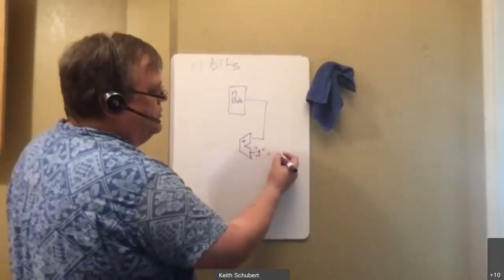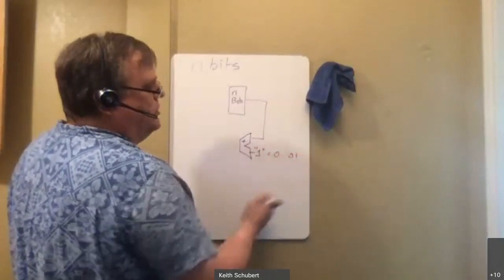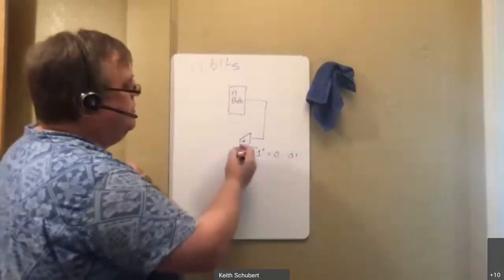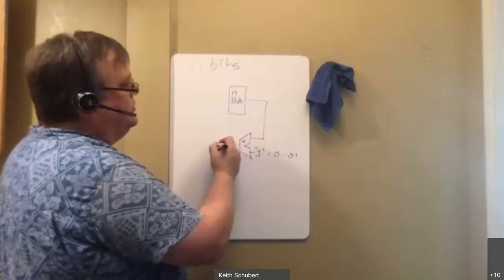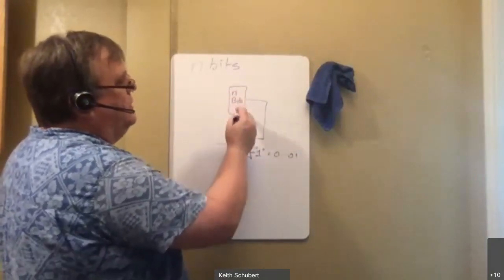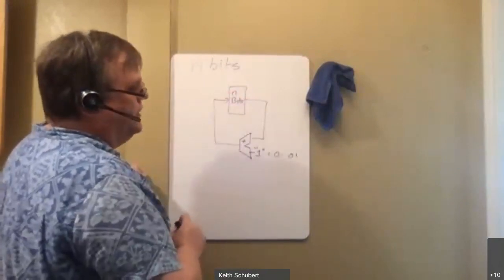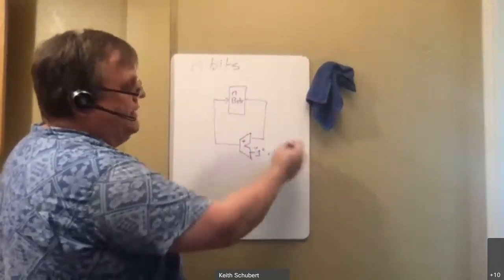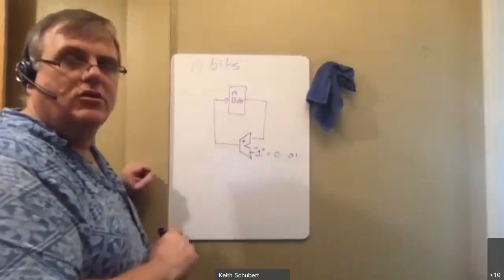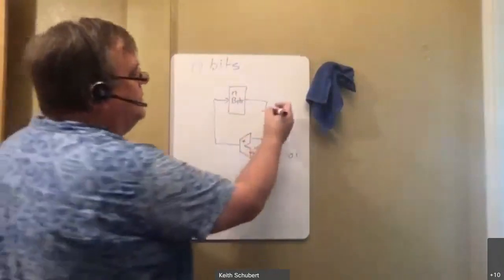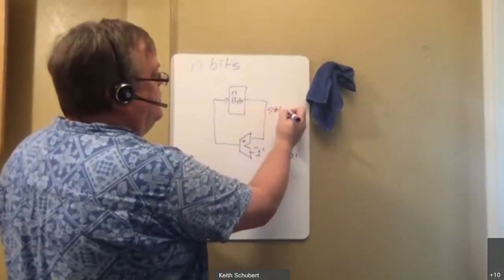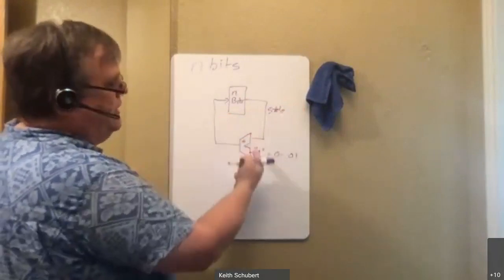This is equal to a whole bunch of zeros and then a 1. The output of this is going to be n bits that's 1 bigger than this. And I just run it in. So this technically is my next state logic. So if this is my current state, this is now state plus 1.